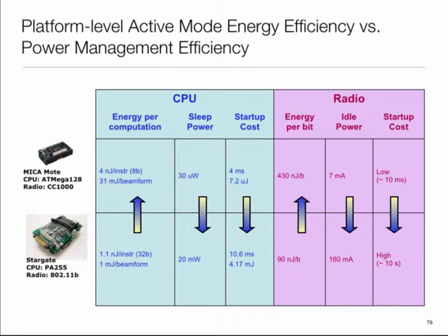So these things end up overall winning out when it comes to energy per bit. But all that stuff increases idle power, and it is also a more complicated device, so it has more state, and saving and restoring that state takes more time. So this is perhaps at some level inevitable. Small things are more agile, but when faced with heavy duty tasks, they are less efficient, and we see that again and again.